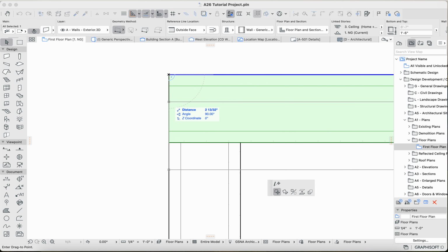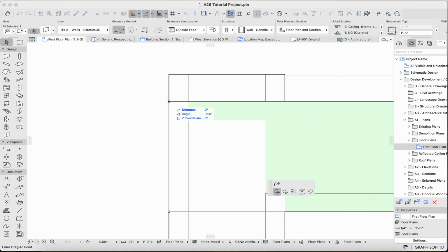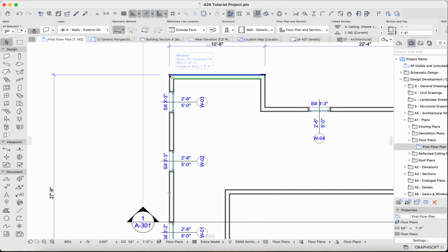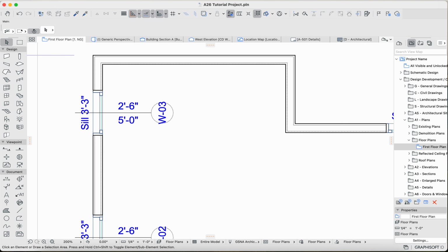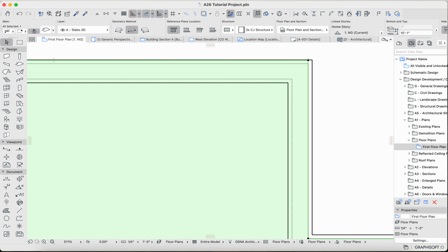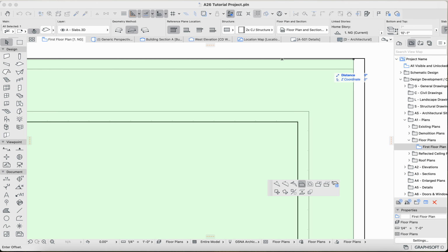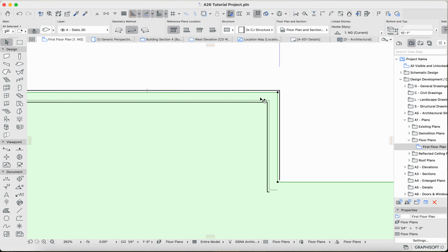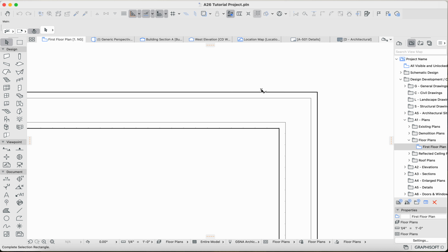Alright, now he's quiet. So I'm going to select this other wall, and then I'm just going to drag it back to this corner here so that it intersects properly. And then I'm going to hold shift and left click, and then I'm going to intersect those two walls. And there we have it. This finished material is sticking out a little bit, so I'm just going to select that edge and then offset it about an inch, and that should do it.